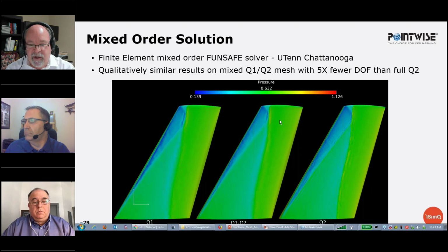Typically, we've used convergence criteria looking at the percentage of the mesh nodes that are actually being adapted. And this starts off small, maybe only 20% or 30% of the nodes, but as the discretization error becomes uniform, which is what we're driving it to become, then more and more of the nodes are involved in the next adaptation step. So we would stop, let's say, when 90% of the vertices are indicated for adaptation. And lastly, we've chosen to use 2-point clouds most of the time for any particular step we're making, and this really helps smoothness of the process and stability of the process as well.